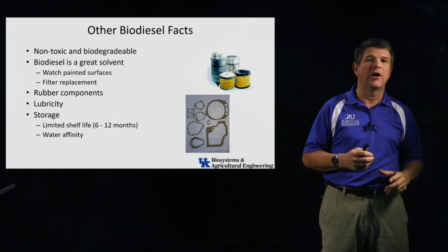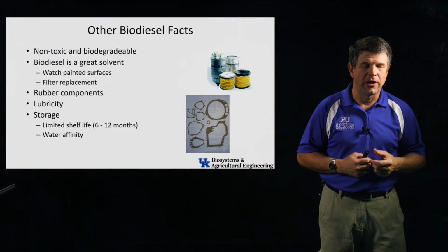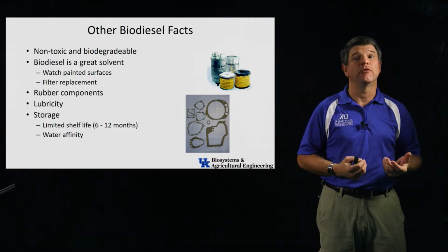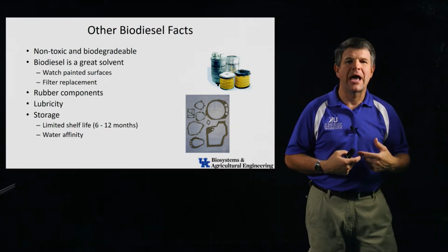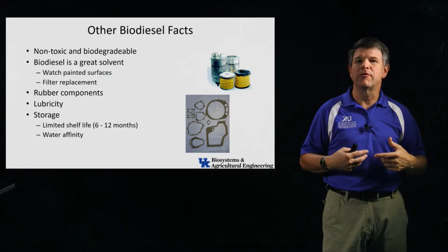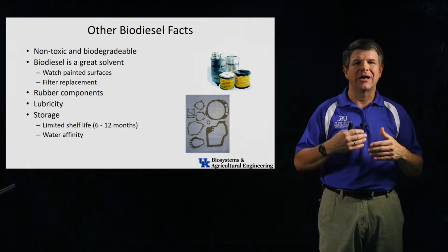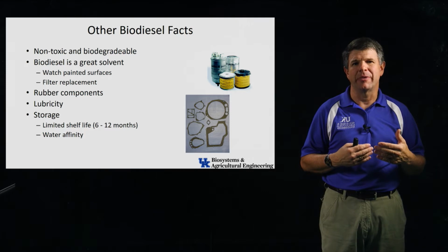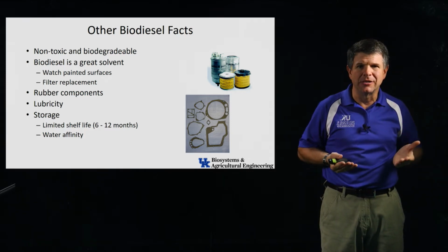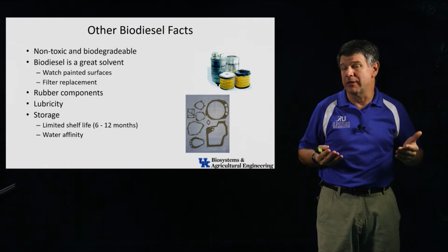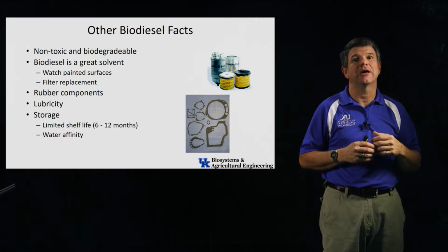So they took the fuel filter off, put a new fuel filter on, ran it for another hour, it shut off, looked at the fuel filter, and it was plugged up again. Well, what had happened is petroleum-based diesel, over time, has a lot of paraffins and different wax compounds in it. It'll actually build up on the inside of your fuel system, on the inside of the tank, on the inside of the lines, and all that kind of stuff.